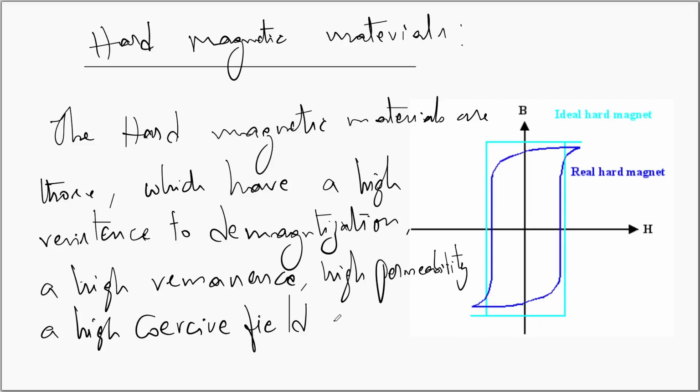The hard magnetic materials are magnetized in a magnetic field strong enough to orient the magnetic moments of their domains in the direction of the applied field. Part of the energy of the applied field is converted into potential energy, which is stored in the permanent magnet produced. A permanent magnet in the fully magnetized condition is thus in a relatively high energy state as compared to a demagnetized state. The power or external energy of a hard magnetic material is directly related to the size of the hysteresis loop. The magnetic potential of the material is measured by the energy product BH max.